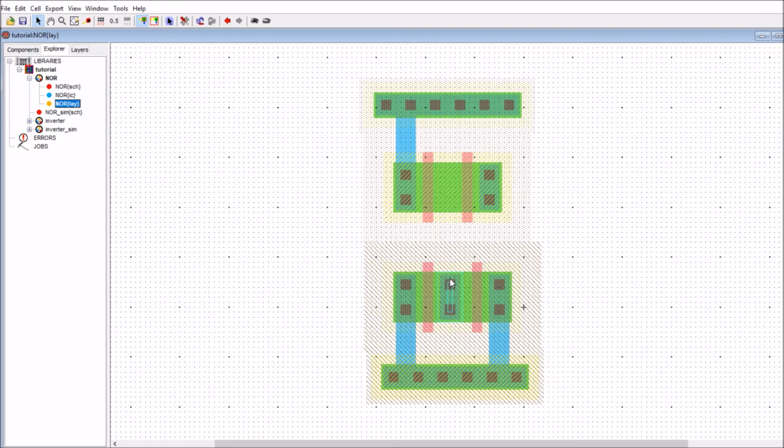Okay, so this is the drain in this thing here. So I can left click, right click, left click, right click, left click, right click. So this is going to be the output, but the output obviously has still got to go up to one of these transistors. So it's not that one because that's the final output, so it must be this one here. So I can left click and right click, so that's that connection up to this one.